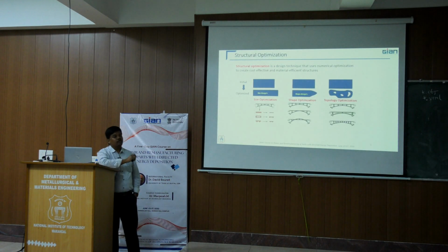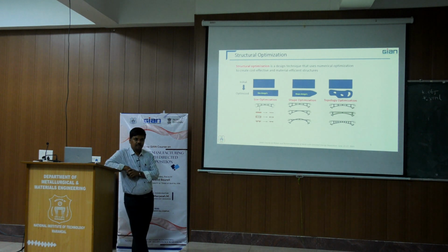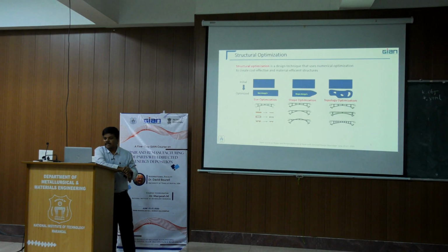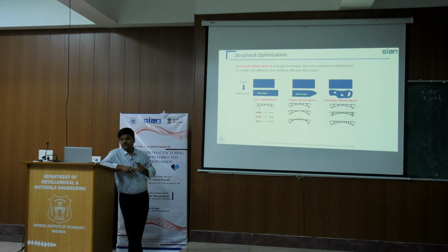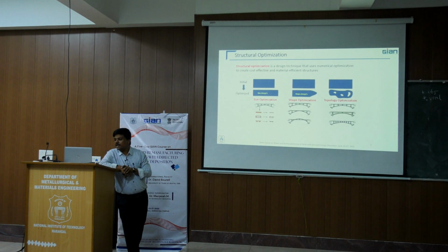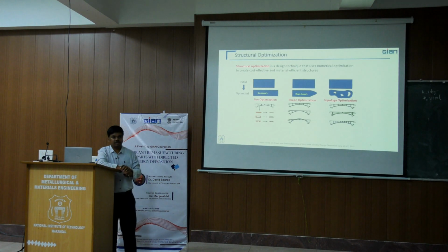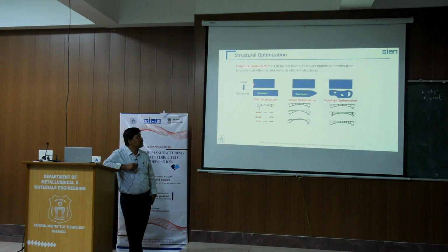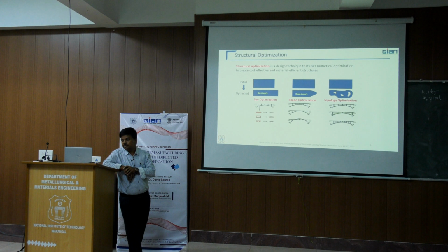And when we say optimization, even generative designs or topology optimizations, first comes structural optimization. It is a design technique that uses numerical optimization to create cost effective and material efficient models of structures. If you see here, this is size optimization. The initial component is very big and then we have optimized to minimize the size, and it may be a shape optimization and it may be a topology optimization.